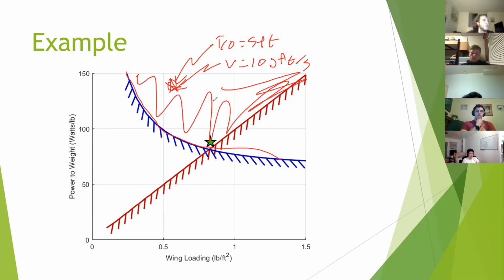And then you also get to use this design space of wing loading versus power loading to iterate through a bunch of scores, right? And so if you calculate the takeoff distance and you calculate the speed and you calculate the optimal weight for each of those points and figure out how much payload you can carry and figure out how long you can fly, make sure you can meet the 200 watt-hour limit.